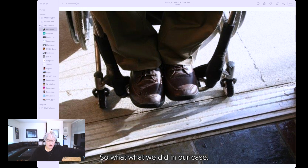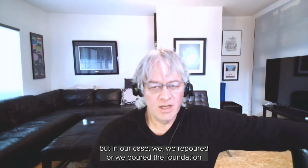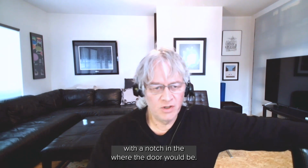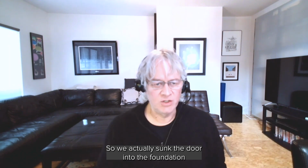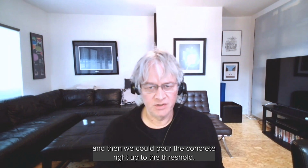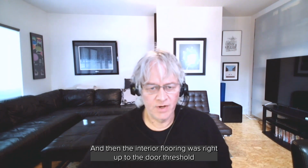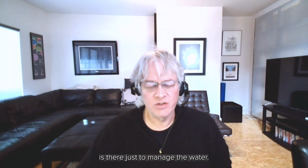So what we did in our case, when you think this through, you can come up with different ideas. In our case, we poured the foundation with a notch where the door would be. So we actually sunk the door into the foundation, and then we could pour the concrete right up to the threshold, and the interior flooring was right up to the door threshold. And that little quarter of an inch bump is there just to manage the water.